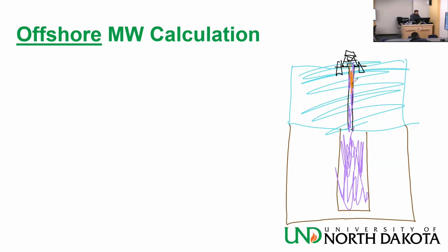There is motivation to put inside the marine riser a different density fluid if you can. This is the basis behind the dual gradient drilling approach I was telling you earlier. We're going to see in module 5, if you do this, you are going to get easier casing design. And you want that, but you don't always have the facility to do that. Chevron has a drill ship dedicated to this task, because then you need to bring mud separately up from the well and mud separately up from the marine riser, etc.